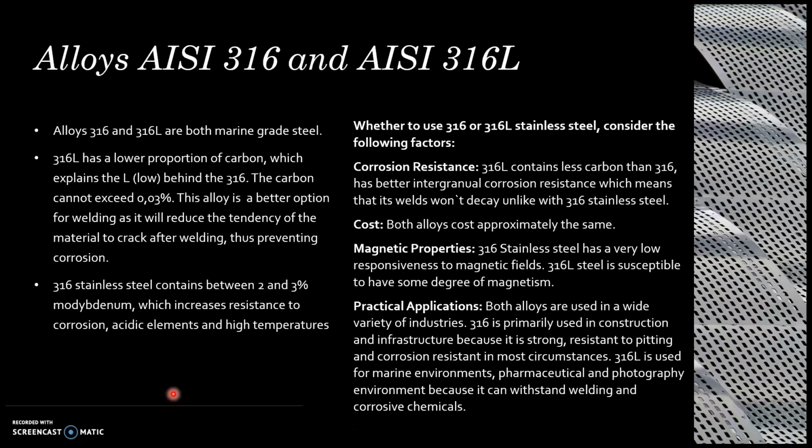Whether you should use 316 or 316L stainless steel, you should consider the following factors. Corrosion resistance. 316L contains less carbon than 316. It has better intergranular corrosion resistance, which means that its welds won't decay unlike with 316 stainless steel.